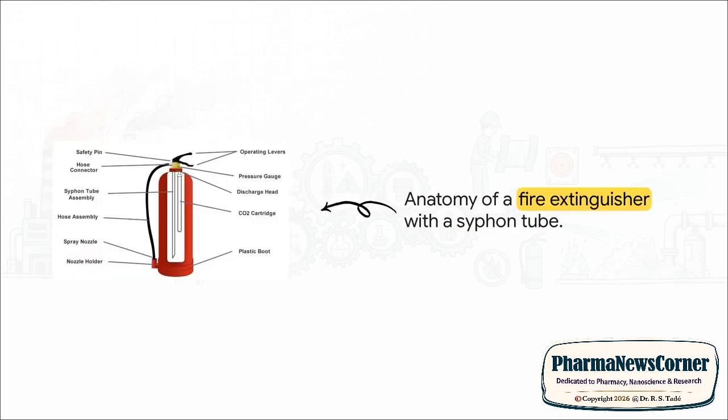And that same targeted engineering goes right into a portable fire extinguisher. Inside that heavy metal cylinder, there's a siphon tube running down into the suppressive agent, which, by the way, could be powder, foam, or a wet chemical. When you pull the safety pin and squeeze that lever, it pierces a highly pressurized CO2 cartridge. That sudden release of gas violently forces the agent down, back up through the siphon tube, out the spray nozzle, and right on to the base of the fire.